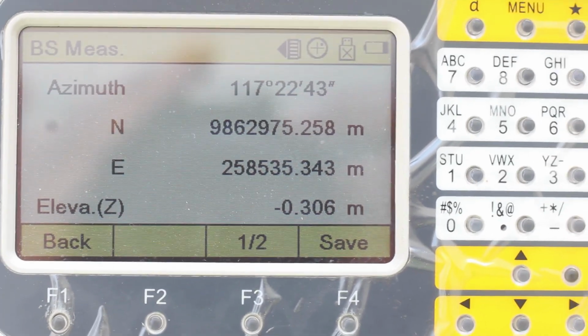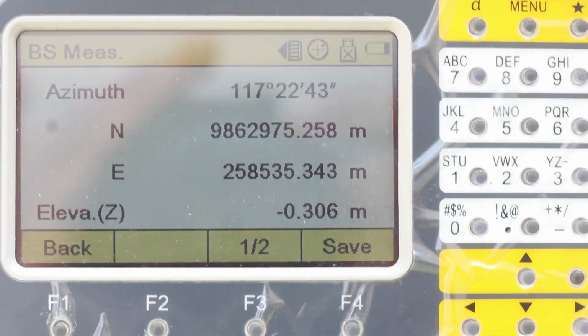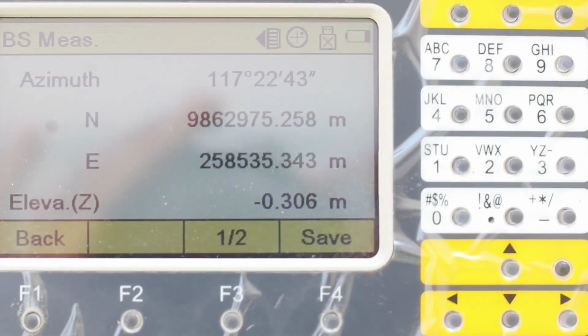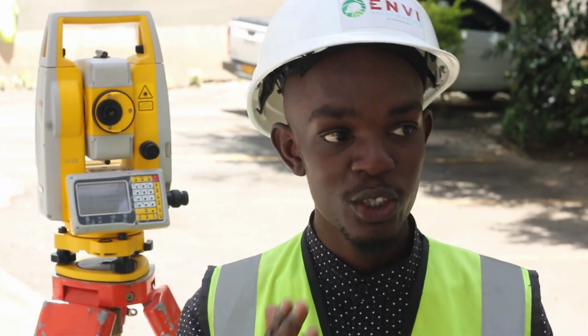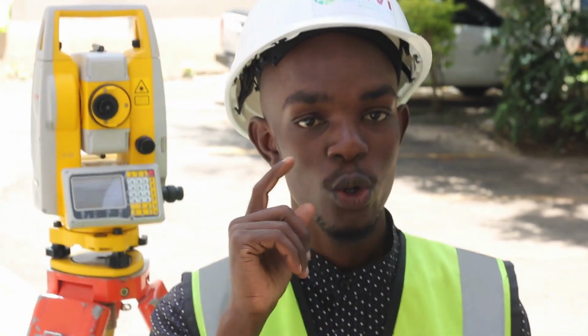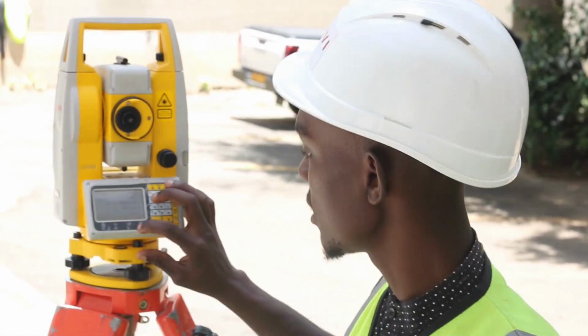The easting is 0.343, while the theoretical coordinate is 0.34. That is a 3 millimeter difference. These two are allowable errors. I have checked the coordinate of traverse point number 2 and it reads correctly. Once I am certain that it reads correctly, I click save.